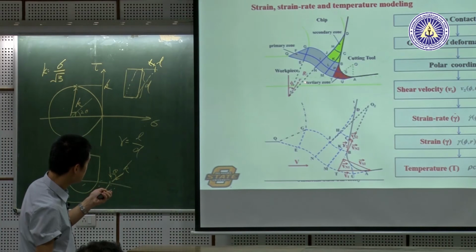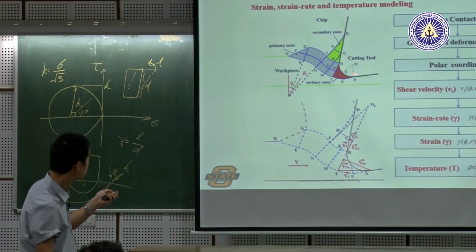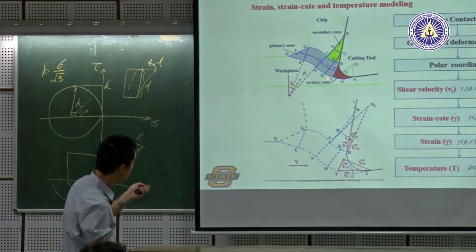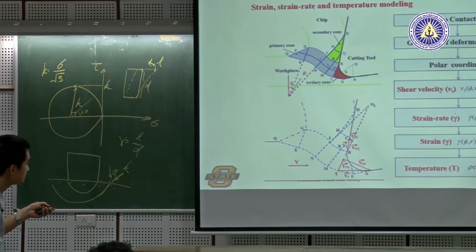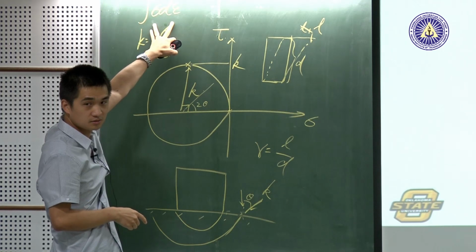Based on this model, the strain here is always 0 because it still belongs to the original workpiece. Then the final strain is an accumulation; it increases in a linear pattern gradually from the original to this end part. Then we model this strain based on this polar coordinate. If the strain happens, then strain times strain rate is... Anyone knows, let's say epsilon is a strain and sigma is a stress, stress integral with respect to strain, what's the unit?